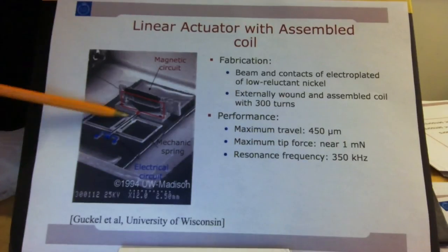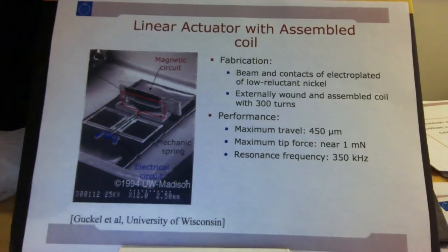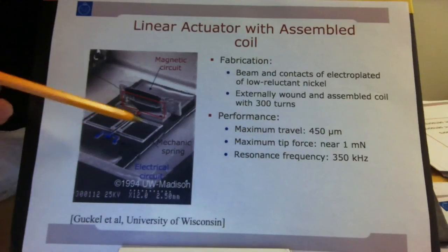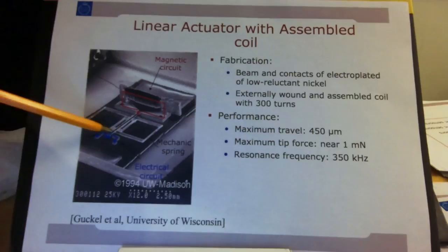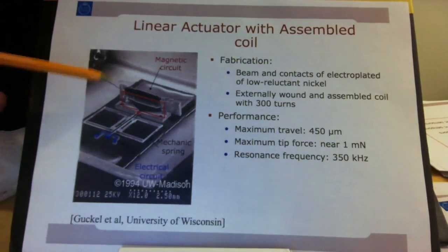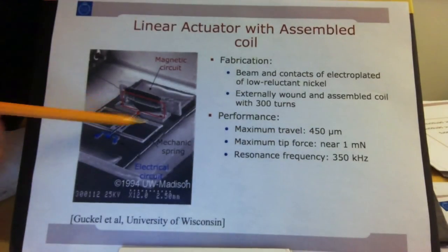So how are we going to move this bar here in the middle? Well, this bar in the middle is suspended on a spring structure, and you can see that here. There's a silicon arm here, here, and here. So there's 1, 2, 3, and 4 U-arms that suspend this moving middle arm to these 4 fixed posts. So basically this arm can move freely up and down. This is a spring system keeping it in place. And why or when does it move? Well, that is steered by the magnetic circuit here.